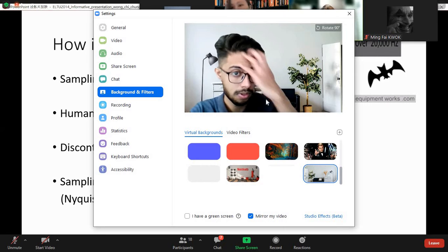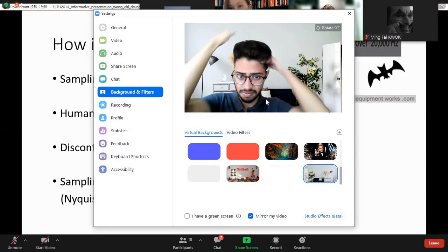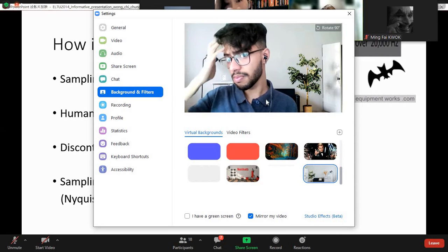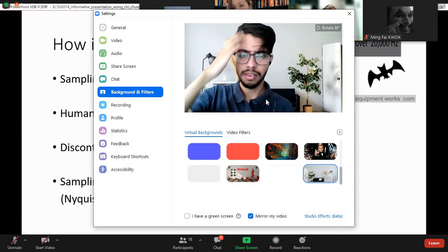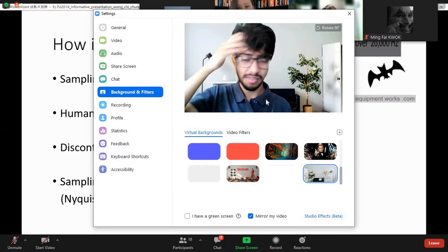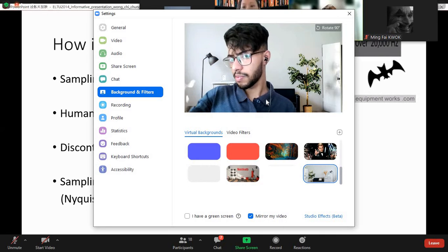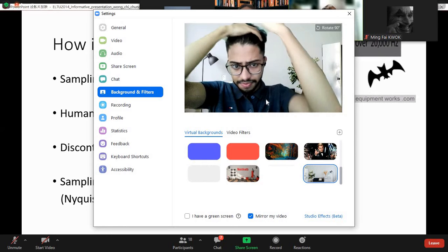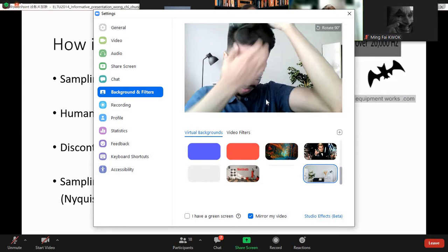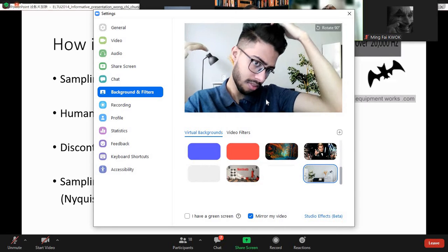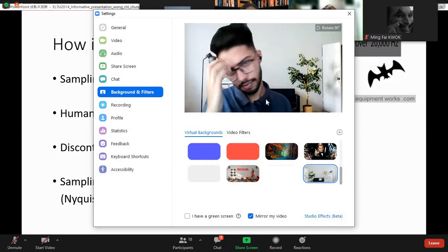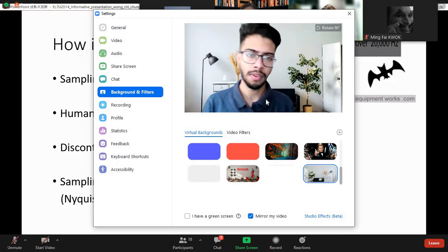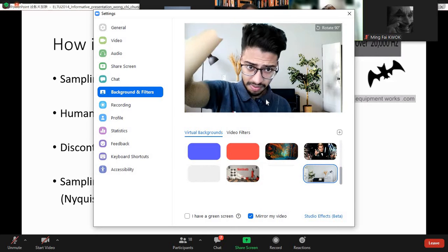The other factor is the sampling frequency. Most DACs have a sampling frequency of 44.1 kilohertz. And why is this specific number? Because the human hearing range is between 20 hertz and 20 kilohertz. If the sampling frequency is too low, we can identify the discontinuity of the discrete digital signal. So past scientists discovered that the sampling frequency should be double the maximum hearing range, which is 20 kilohertz times 2, 40 kilohertz.